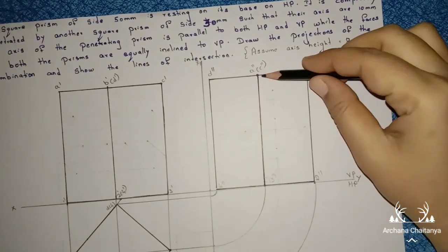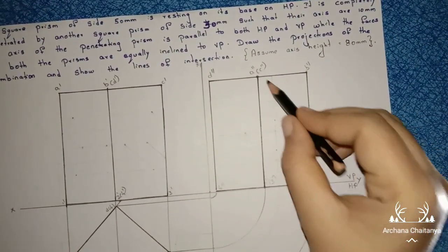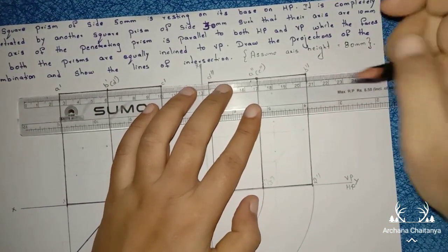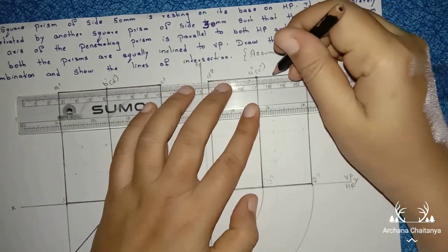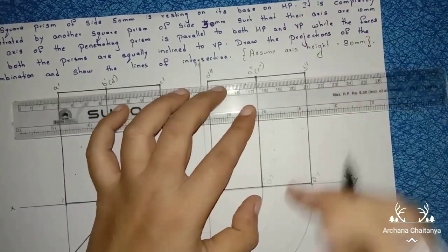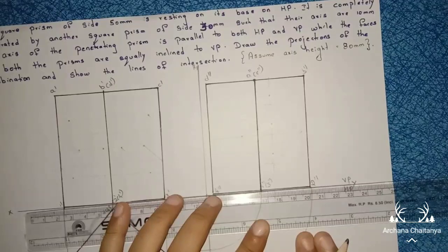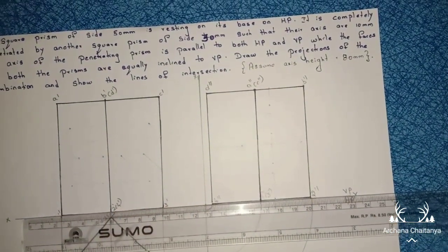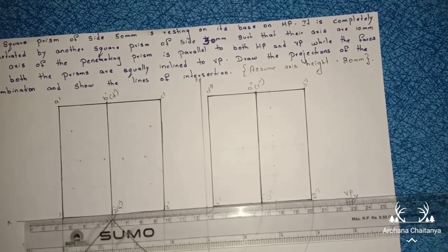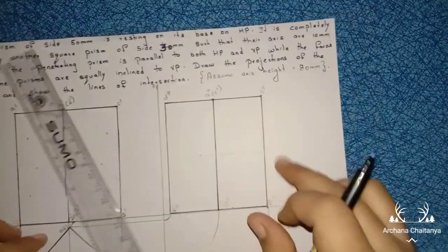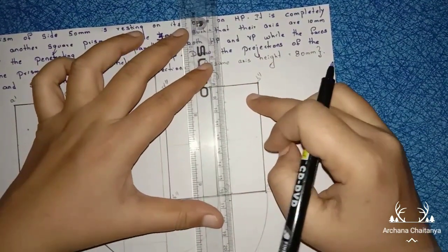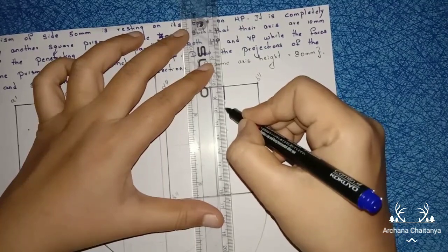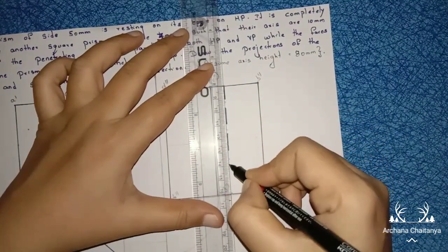Right, actually this is your axis line. Now from this axis line mark 10 mm distance here. Again from this axis line, on the top face and bottom face also, mark 10 mm distance. They clearly mention that axes are 10 mm apart. After marking 10 mm distance, now through that point construct the axis line. The axis line should be dash-dot, so construct the axis line.